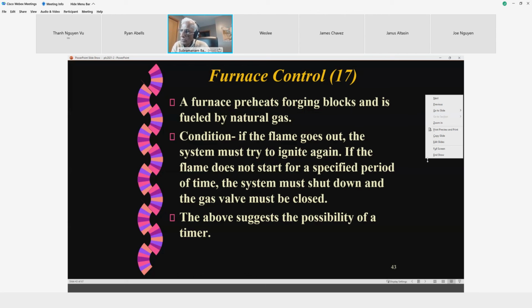You don't put natural gas inside the furnace all the time. You have a shut-off valve for the entire house that's always on unless there is an emergency. But within the furnace, there is another valve, which is electronic, which is going to be controlled by the controller that we are going to develop.